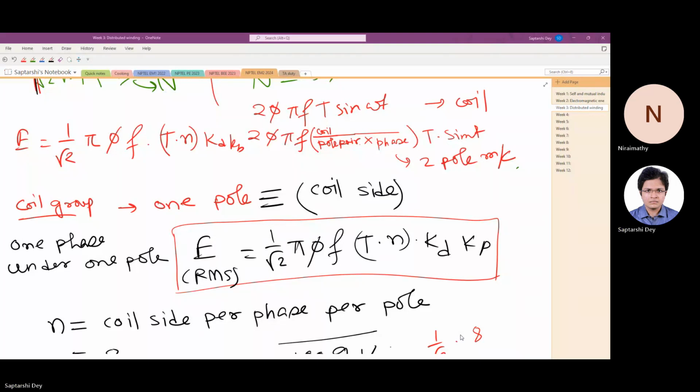Does it go? I may be wrong though. Short circuit condition, your winding will burn, and your magnets may burn, may demagnetize completely. Short circuit, high current will not increase the core temperature that much. If there is a high amount of alternating current flowing continuously, that will increase the core loss. But before that, it will trip due to short circuit, not due to the core temperature increment.